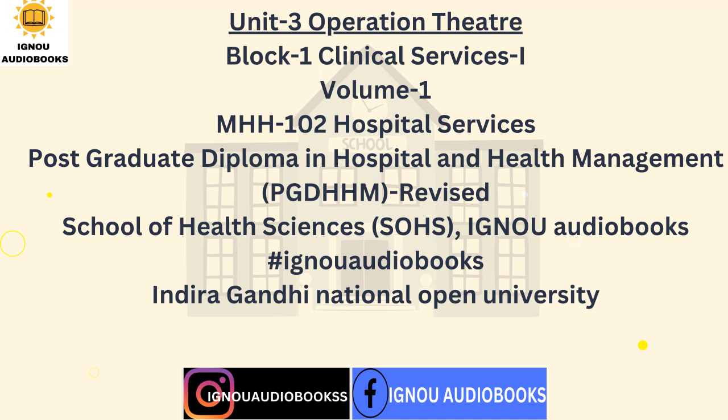3. Hospital support service facilities like CSSD, Central Sterile Supply Department, X-ray, laboratory and blood bank should be preferably in its proximity as far as practicable. The unit also needs constant specialized services such as piped suction and medical gases, electric supply, heating, air conditioning, ventilation, and efficient lift services, if theatres are located on the upper floor in the multi-story building.